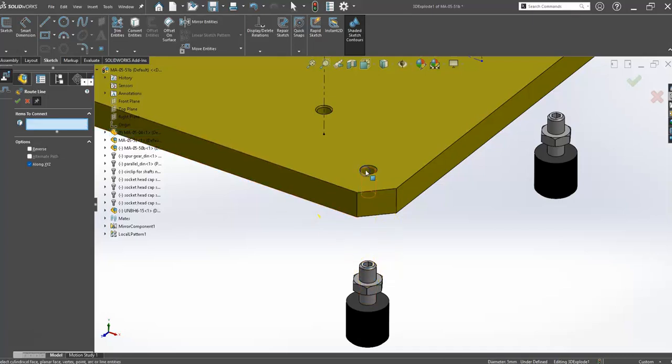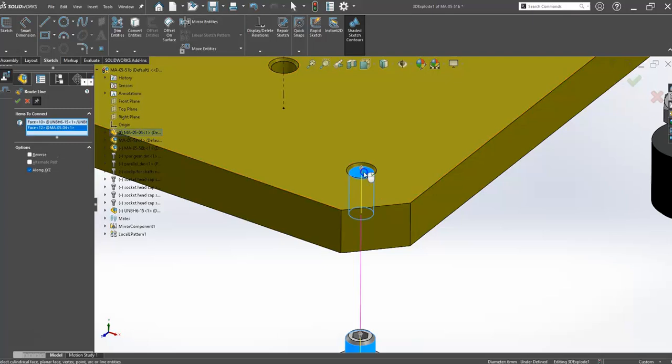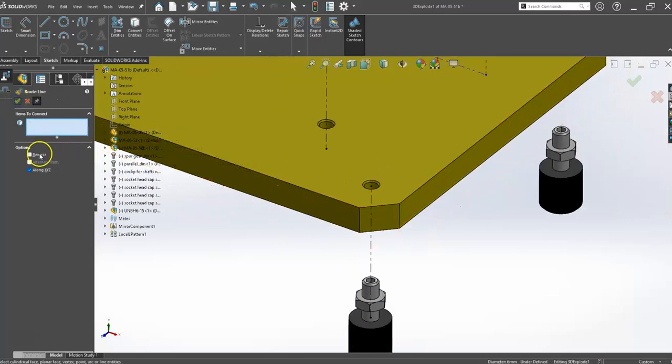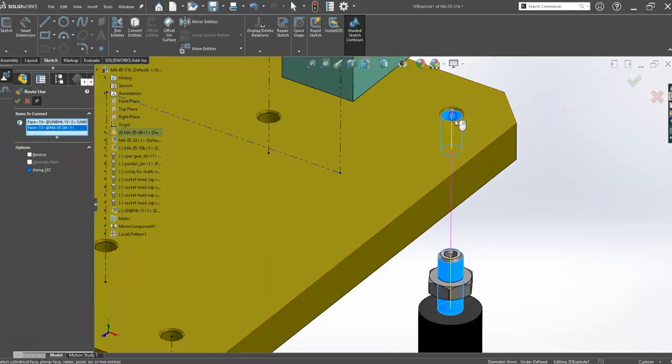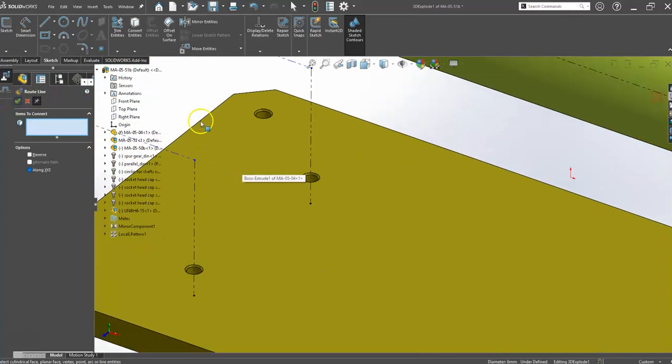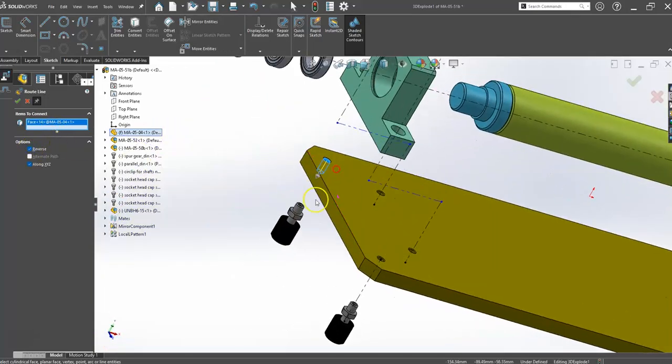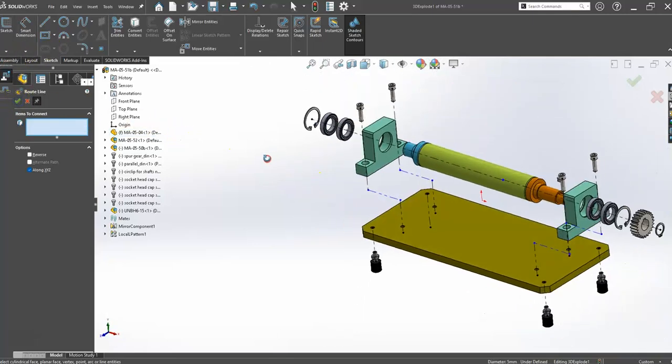I just select that twice, one selects it, then select the bottom one. You have to watch the direction of that wee arrow. There's a wee reverse here if you need to reverse it. So again, I'll reverse it now, maybe in the next one. I'll hit OK. If I pick the plate first, for example, I'll hit reverse and the arrow goes down the way, and then I'll pick the bottom part. So it's the same thing, only in reverse. So that's kind of the part done.